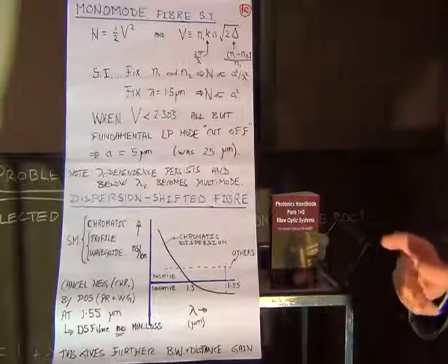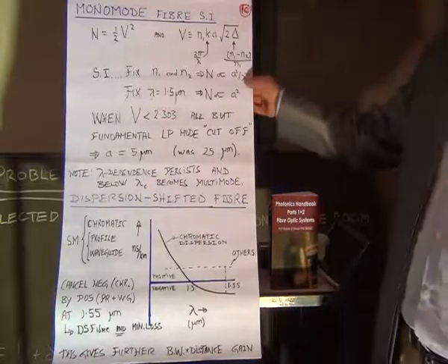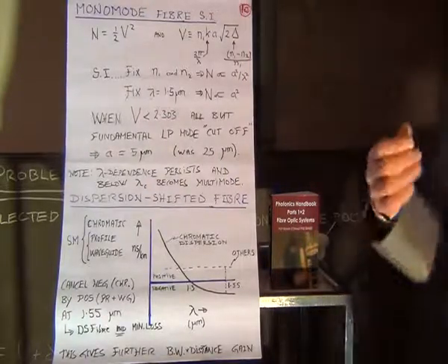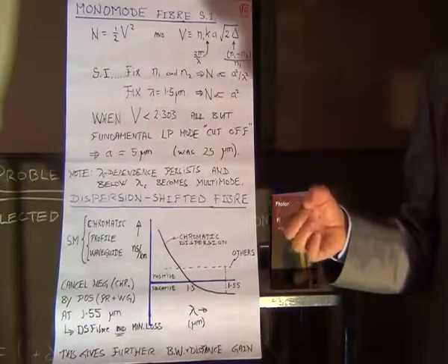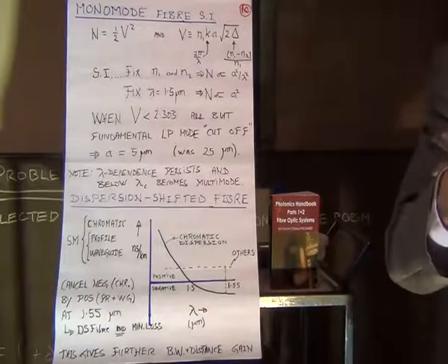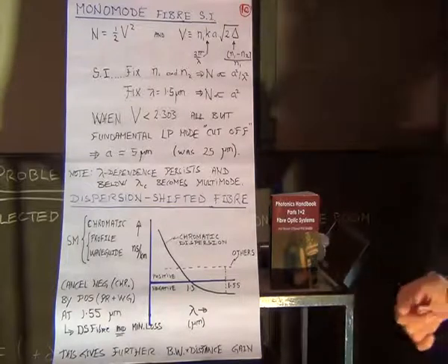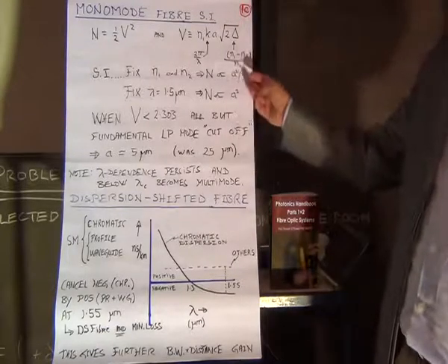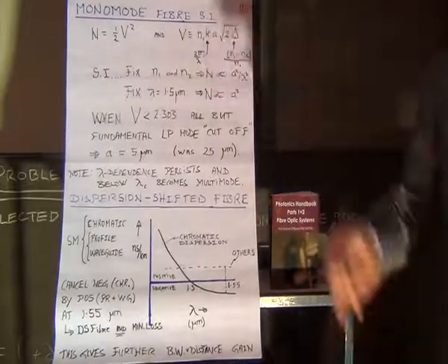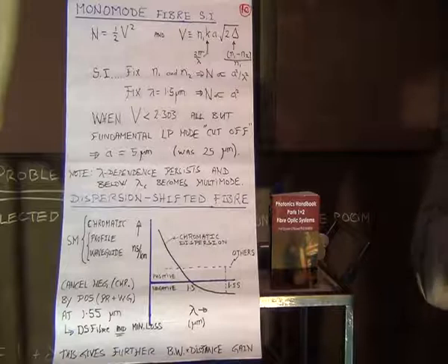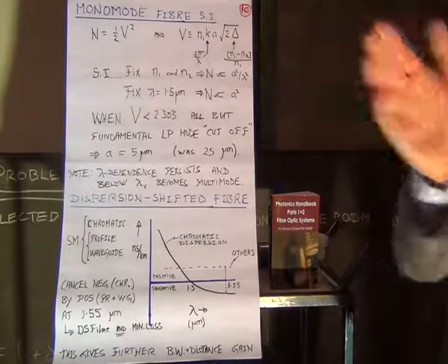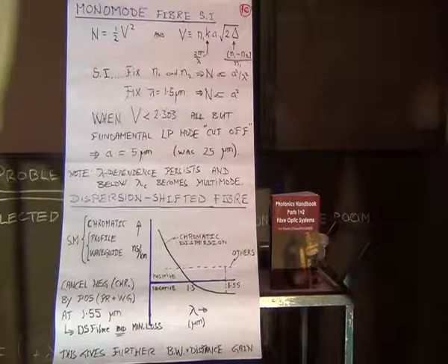single mode fibre, if you now start to change the wavelength, say you're working in C band, 1.5 microns, and you say, I'm going to try it at 1.3 microns, S band for some other reason. Well, what happens then is if you go back to N, you find a second mode appearing. So there is a wavelength for every optical fibre called the cutoff wavelength, and you must not go shorter than that wavelength or it becomes multimode all over again.